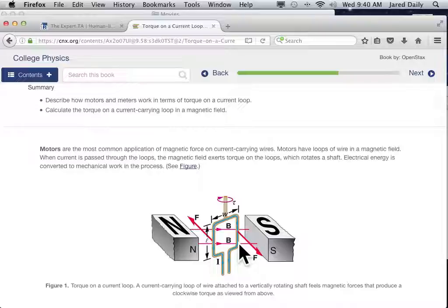If you take a force, it's going to make it spin, right? If you take a force and put it on one side of an object going one way and the other side of the object going the other way, it turns the loop. It creates a torque, like we learned last semester. So it's going to rotate this loop as long as that loop is free to rotate. And that's what we do. We put that in the center of that loop, right down here. We put an axis with a little ball bearing thing or something, and we let it spin that way, right?